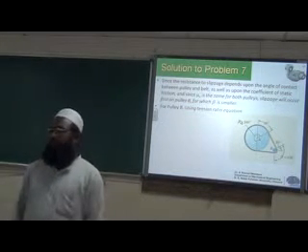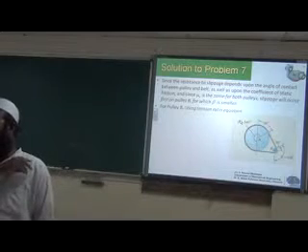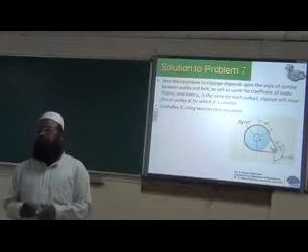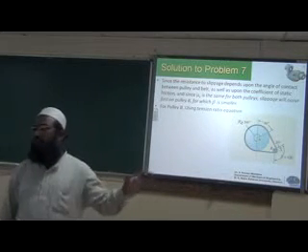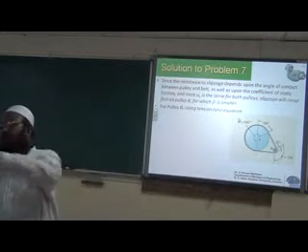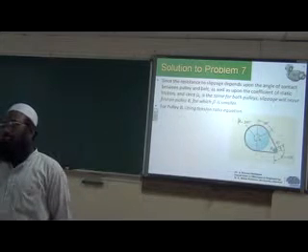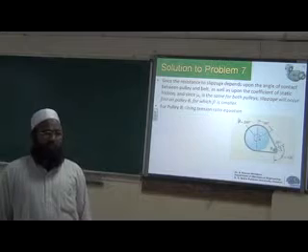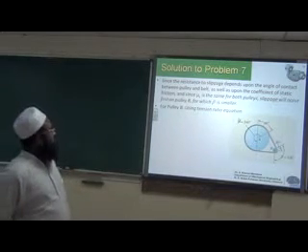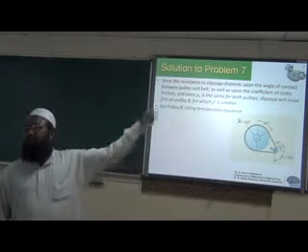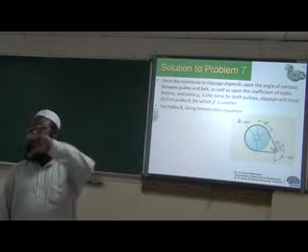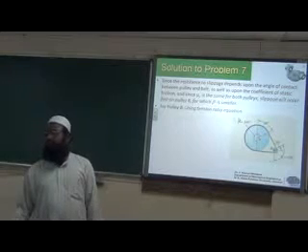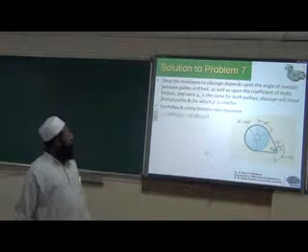So if you consider both the pulleys, the smaller pulley is having less angle of lap. So what will happen? Where the slip will be more, since there is only less contact in the smaller pulley, slip will be more in B, in the smaller pulley. So we have to consider first the T1 by T2 equation for the smaller pulley, and we find out the tension.